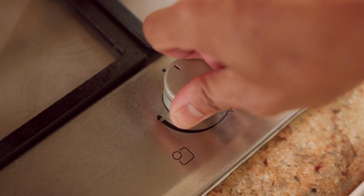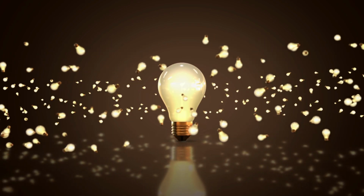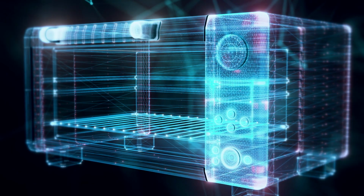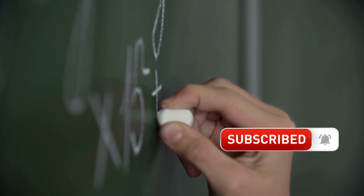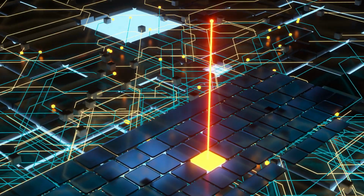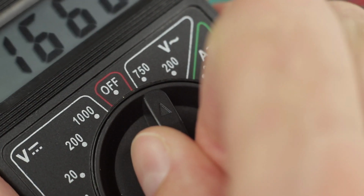Your home's electrical consumption can be measured in watts or kilowatts for every appliance that requires electricity to function. For instance, a light bulb might be 60 watts, while a microwave might be 750 watts. It is simple to quantify watts with a simple equation that may be applied to a wide range of contexts. Knowing the current and voltage of an electrical system allows us to determine the power output in watts. A multimeter is used to measure both voltage and current.